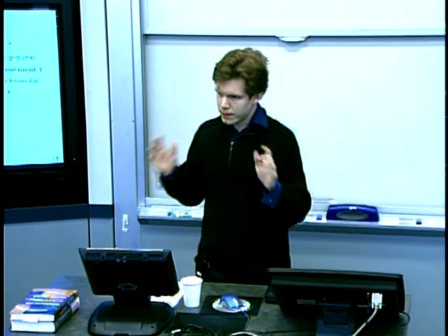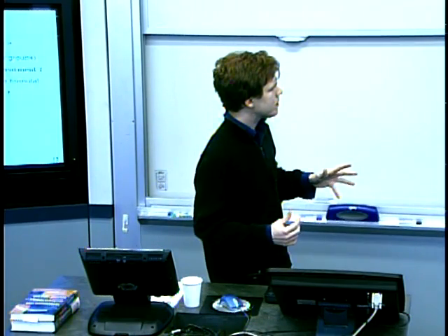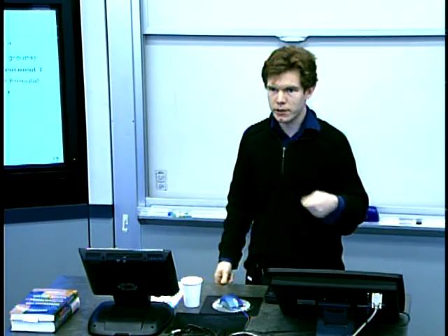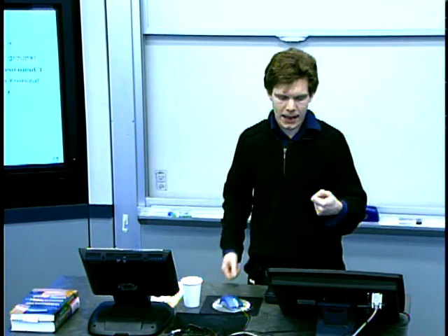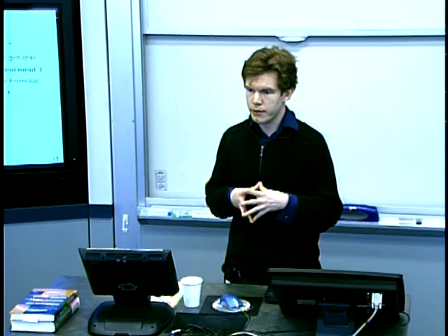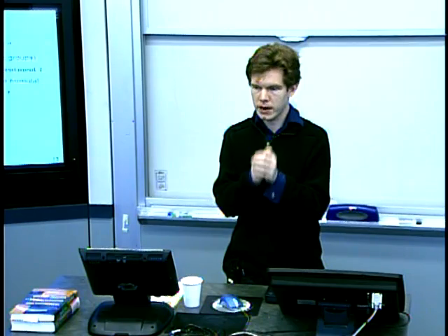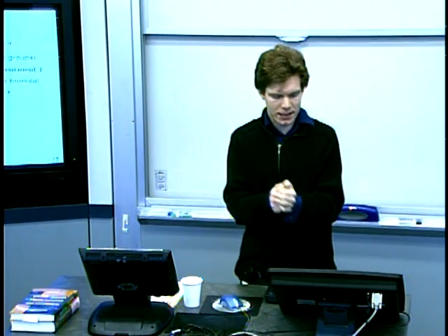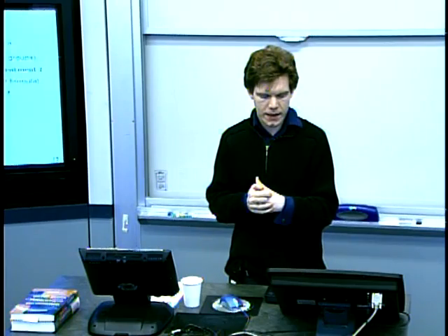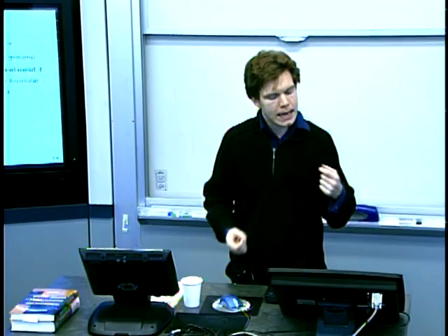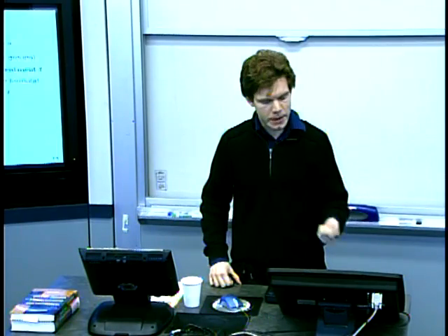I'm going to go through each of those steps in turn and go through the mechanics of how we're going to do that. I've already said that we're assuming that the output for each group, and by group I mean the parts sampled for a given treatment, so for a given setting of the input variable, we're saying that variation is described by a variance of sigma naught squared, and it's the same for each group, which may be true or may not be, in which case we need to go back and think again.